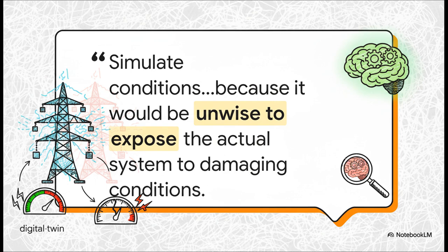And here's why that is so important. And I'm quoting directly from the standard here. A load flow study lets engineers test for things you would never do in the real world because it would be, quote, unwise to expose the actual physical system to conditions that are potentially damaging. It's the ultimate sandbox for designing for the absolute worst-case scenario in a totally safe way.